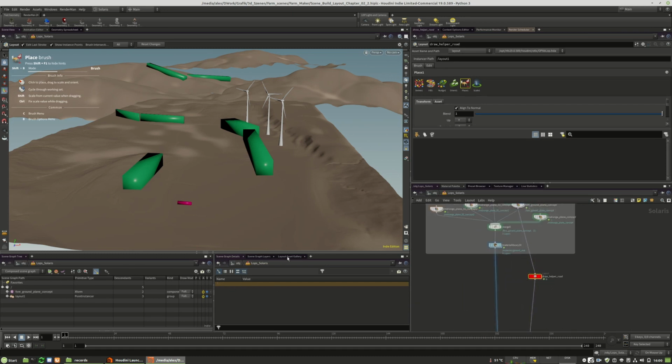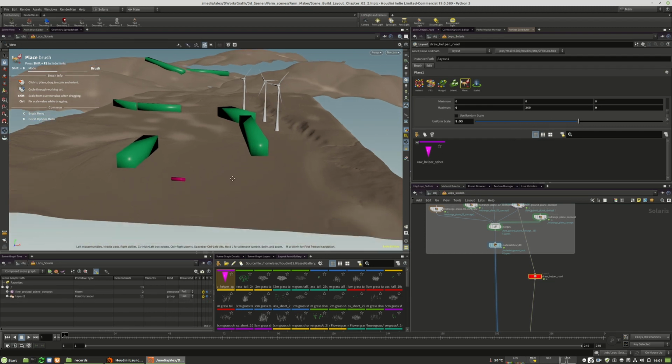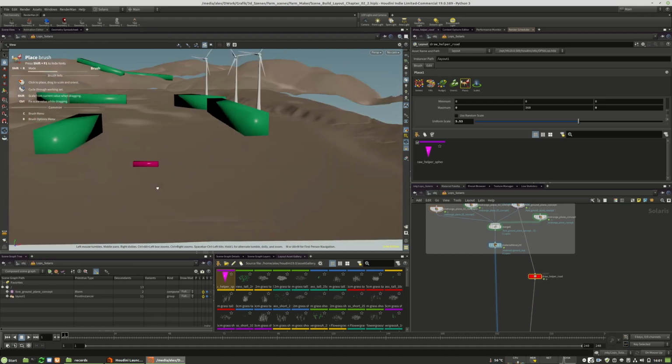So, and now I go to the layout asset gallery that you have to populate by yourself, and I will drag and drop this cone right in here, this violet cone. I will activate it, and now I see the cone right in here. We can of course scale the cone up. We can already do this right now so that we see where we are.